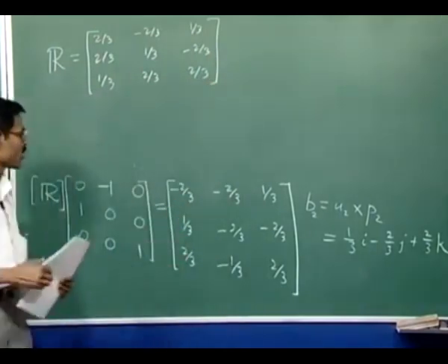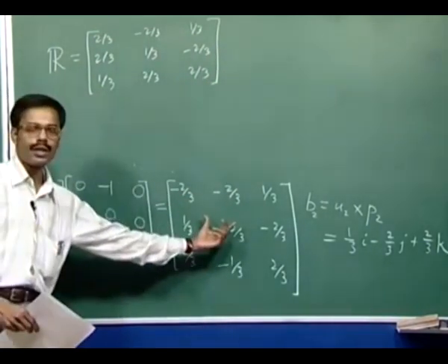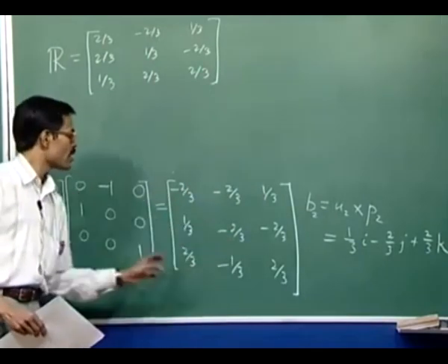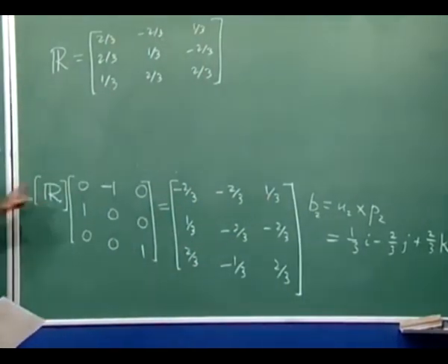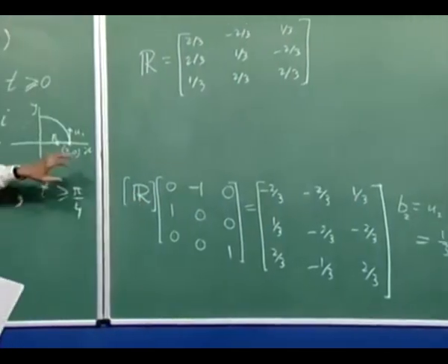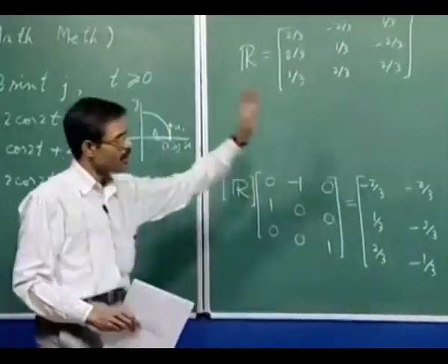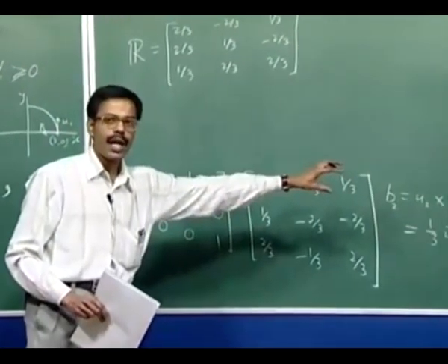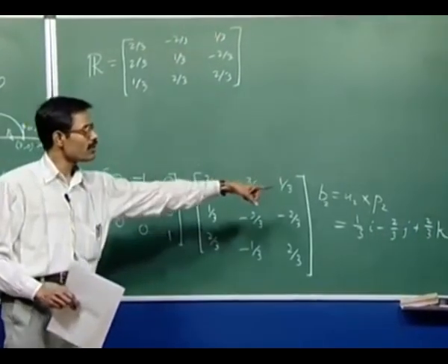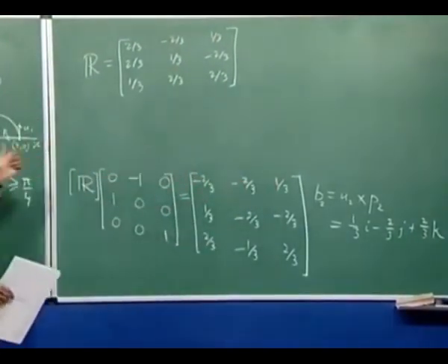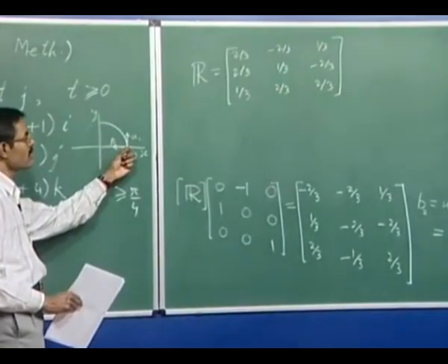So, those column operations which will make it identity, the corresponding column operations done here give the value of the rotation matrix R. Now, this is the matrix R which operated over U1 P1 B1 takes it to U2 P2 B2, and what we are looking for is actually the inverse transformation, because we want the second curve to come and merge here, right, if they turn out to be the same curve.